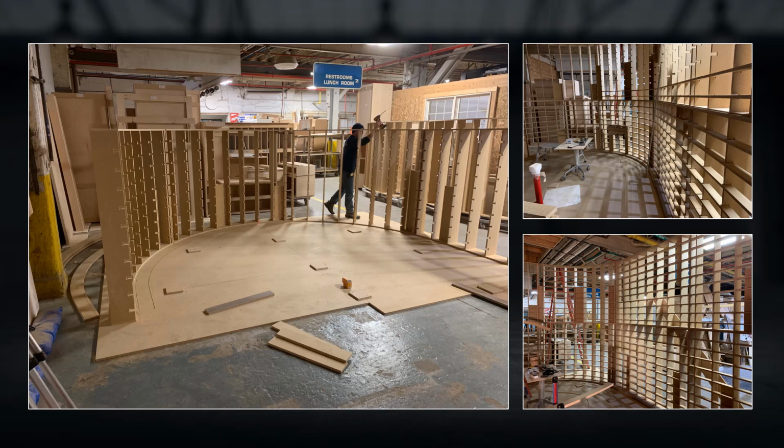Then we cut all these studs, the top plates and bottom plates on the CNC. That's just raw particle board. And you can see in the top right, we laced the wall with a 2 inch runner that projected out of the wall, so that when we made our paneling, we were contacting only the radius, none of the flat of the stud wall, so that we didn't create flat sections in the paneling in between the studs. So we have a continuous radius on the wall.